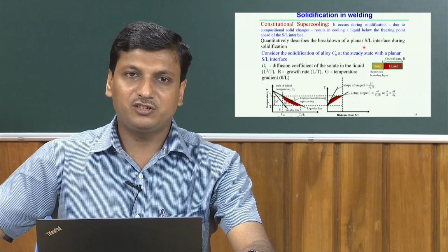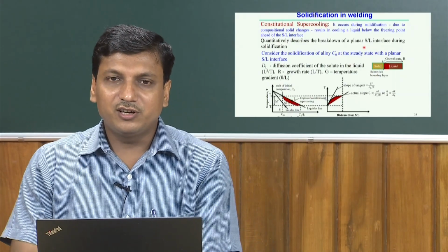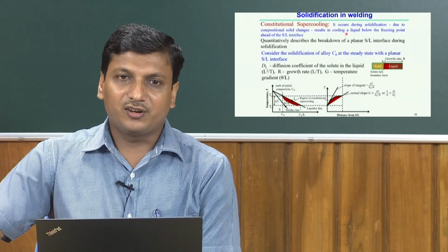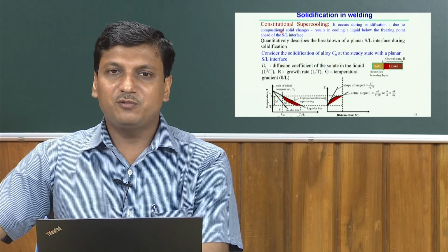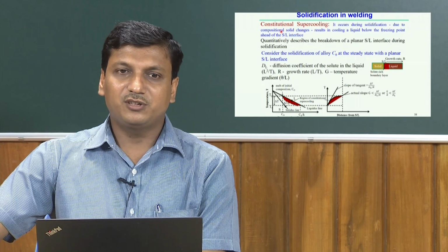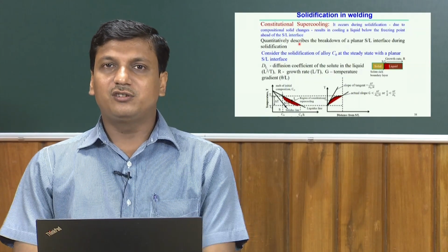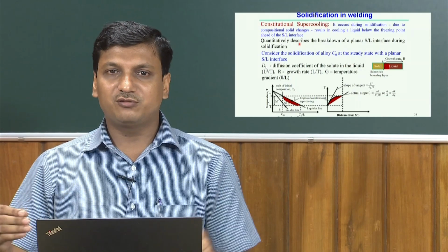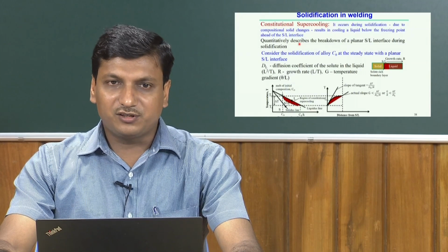Now, in much more detail, solidification in the welding process is very specific to alloy materials, that is, solidification of not pure metal. So, we can say that in the case of alloy metal, constitutional supercooling is one of the important phenomena attached with the solidification during the welding process.